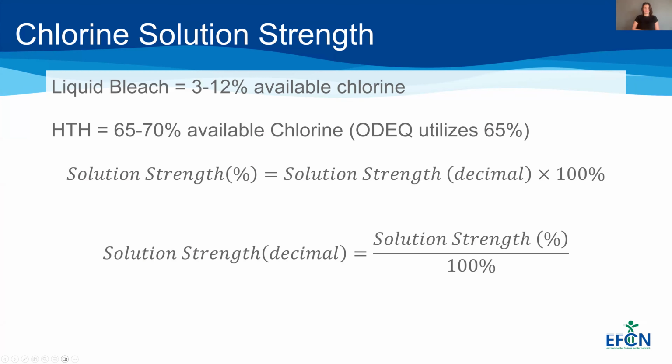When we're working with chlorine, we want to identify what type of chlorine we're utilizing. This can usually be identified by the solution strength. If we're not given a strength, this may just be gas chlorine, and gas chlorine is going to be 100% strength. We use those indicators of the solution strength, or in the practice problems, what type of chlorine is being used, to understand how we might need to adjust our problems.